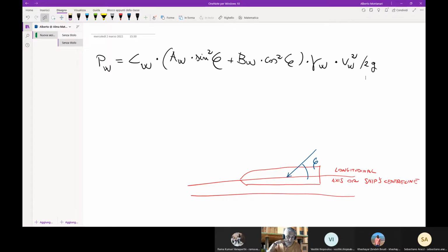We said that we need a probability distribution and a Gust factor. As an order of magnitude, it is recommended that you use a wind speed measured over an interval of 30 seconds with a Gust factor of 1.2. So if you take wind measurements that are taken over an interval of 30 seconds, you have to use a Gust factor of 1.2. As I said, it's like a safety factor.